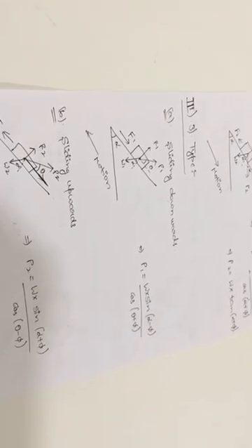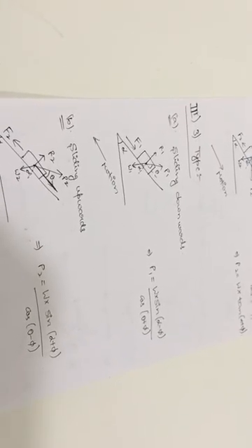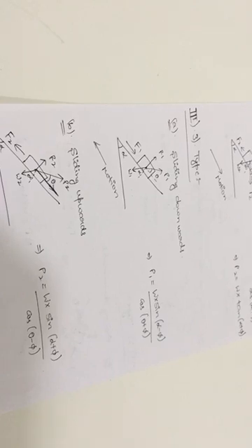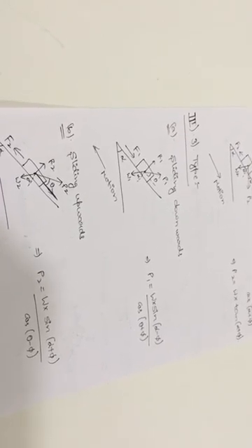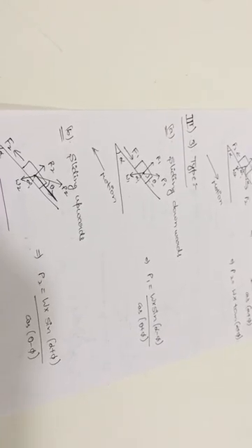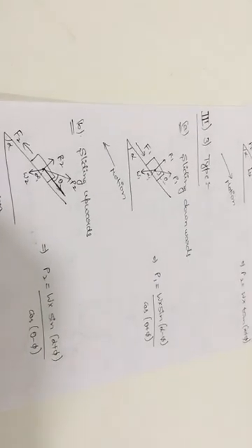And you know that equilibrium conditions, every body will be in the equilibrium condition. So by applying that, compulsorily the diagram should satisfy the equilibrium conditions. So if you apply the equilibrium conditions like sigma H and sigma V equal to 0, you will get the solution. If you do the problem by the formula method or equilibrium conditions method, you will get the same answer only. So in the friction topic, you will get the problems based on these combinations.